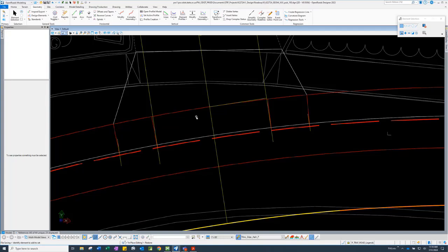So I think to follow suit, and then we've got a chat that I'll tell you about, to just come full circle. The question was asked about why did you draw the control lines and then draw the features over the top of them? And it wasn't evident in the easy picture where you were on a tangent, you were perpendicular, because the feature lines were right over the top of the control lines. And you go, well, why bother? But you like to have a process that you do every time, so you don't have to vary from that process. And it's to draw the control lines and then to draw the feature lines. And in this situation, the feature lines were not directly over the top of the control lines. Correct. That is absolutely the case.